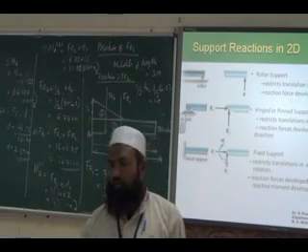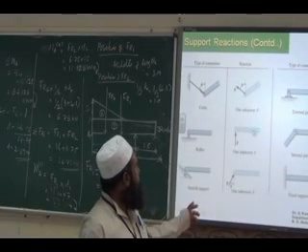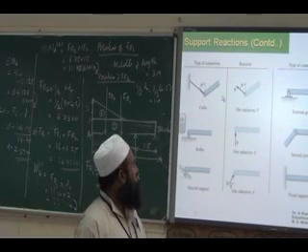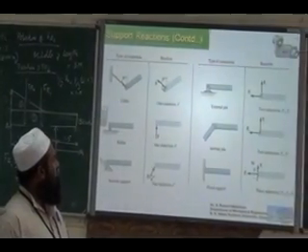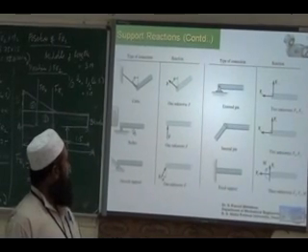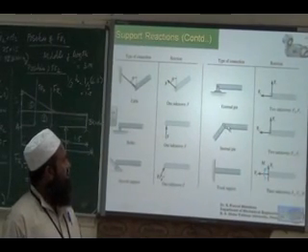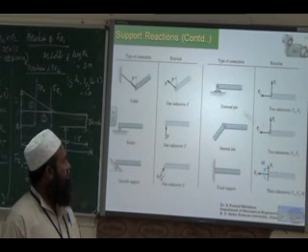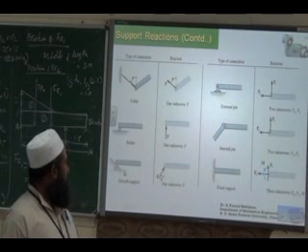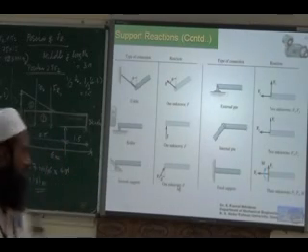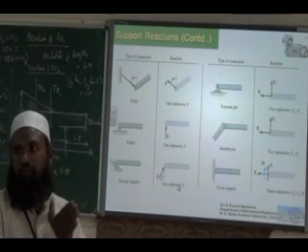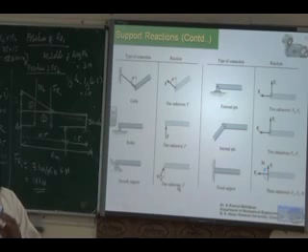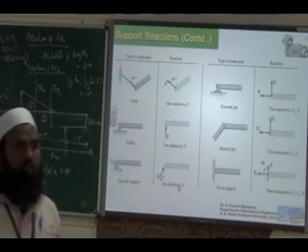So we will have a similar type of reactions. We have a cable. The cable will restrict motion in this direction, so the reactive force is developed. A pin joint, roller. There are another two pins there. It will have the same effect as a pin joint. A slope is there at the end. The reactive force will be perpendicular to the direction of the slope, perpendicular to the surface which is in contact with our member.